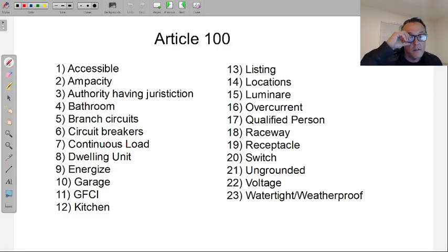This is a bathroom. And again, the reason why you want to know if this is a bathroom versus not a bathroom is that there are codes that follow up with the definition of a bathroom. Has to have this type of outlet in there, must have this minimum wire size, etc. Things that can't be in the bathroom. By the way, you can't have the electrical panel in the bathroom. You can put it in literally any other room in the house.